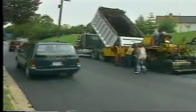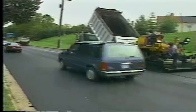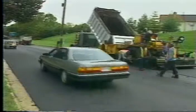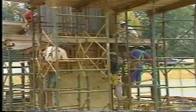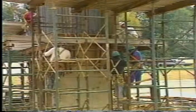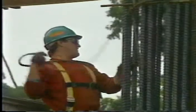There are also recommended planning units of measure for activity groups. For roadway construction, use kilometers. For bridge construction, use 30 linear meters. And others include working days and lump sum.